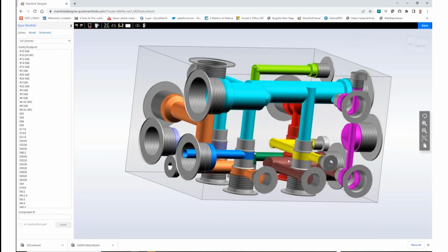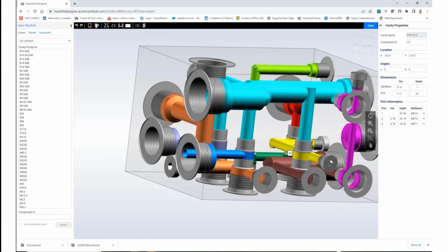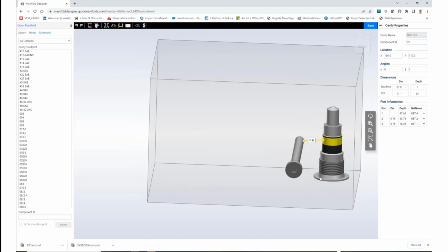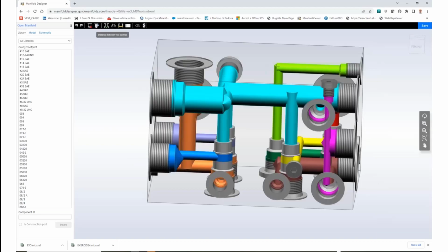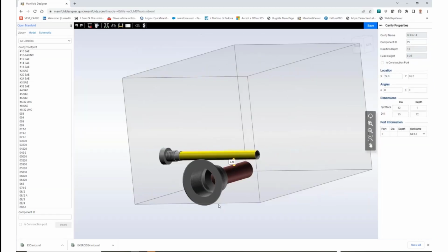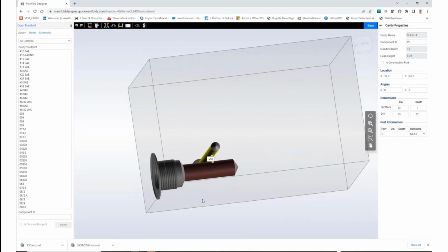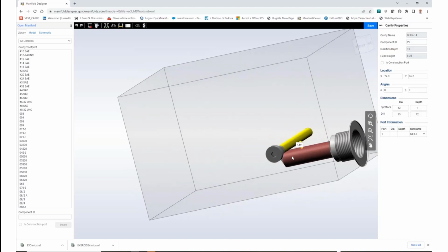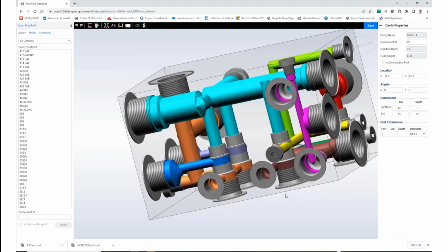Now that I made the distance, I can measure the wall thickness between two cavities. Well, I didn't select the right ones, but as you see in this example, we can isolate the cavities and show the distance between the cavities. So let me select properly. And I can say that this is probably better than MDTools, the way we are displaying the issue.